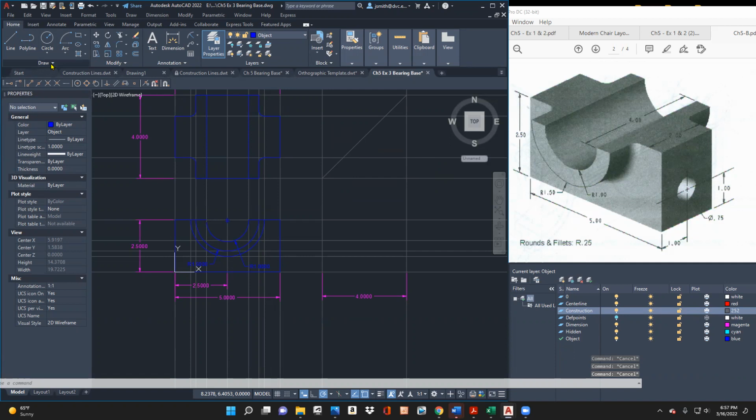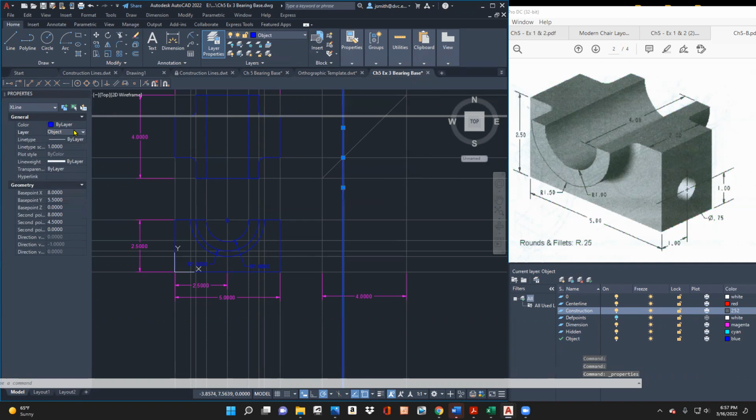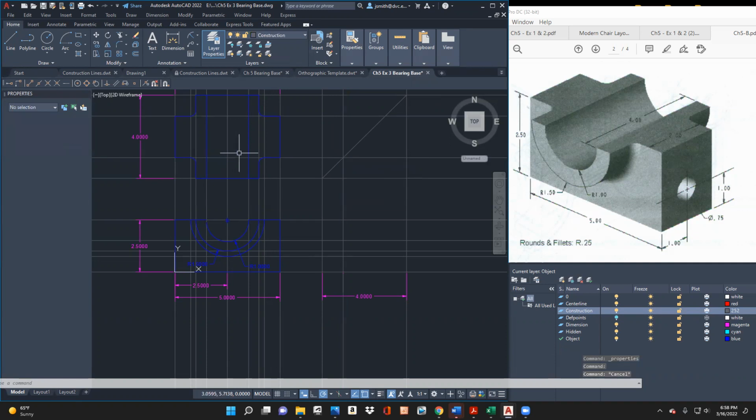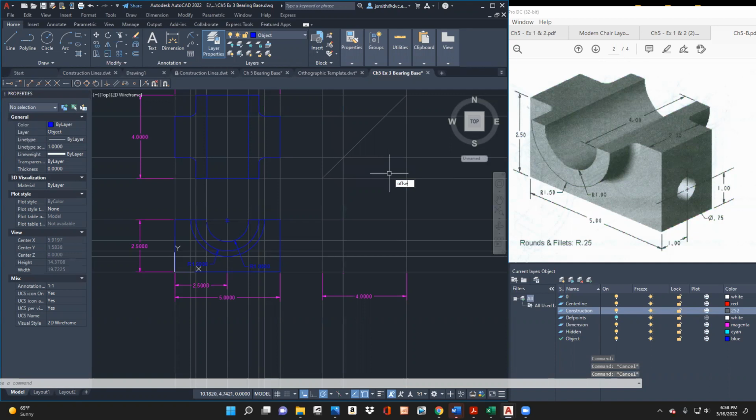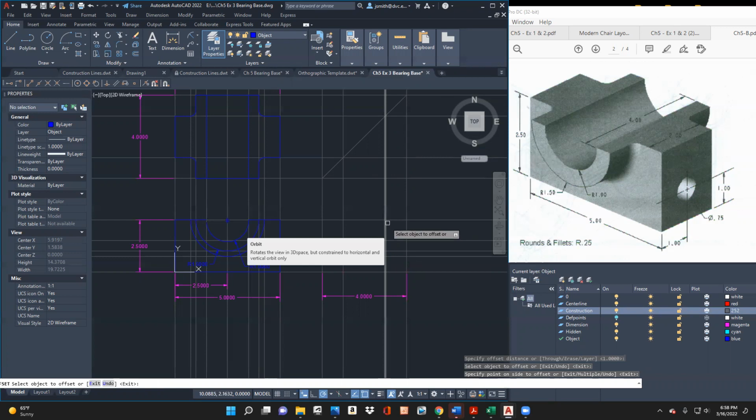Or draw a line. So one way of doing it is you come in here, your construction line, and I would just snap here. We want to be in the correct layer. Properties, put this in my construction. I think you're better off though going offset, select the object here. Let's do that again because I didn't tell. All right, and so this is going to be for the front, it should snap right on that line. That looks good. And I'm getting myself a little confused, but we're going to need the center of this.